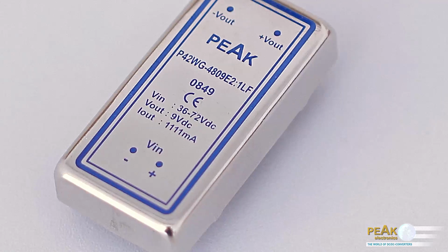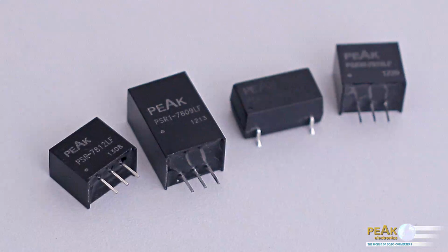This means that the full output power can only be drawn up to a certain ambient temperature. If the ambient temperature is higher, only a lower power may be drawn, and hence the power loss declines, and the converter is no longer so warm. Roughly speaking, the following are given as safe guidelines. DIL 4, 6, 7, 8 packages should have a power loss of 0.5 watt maximum.